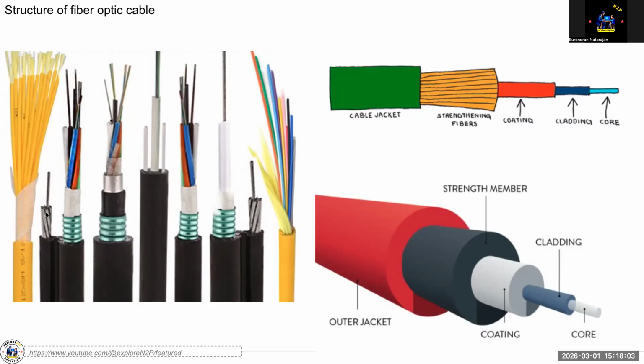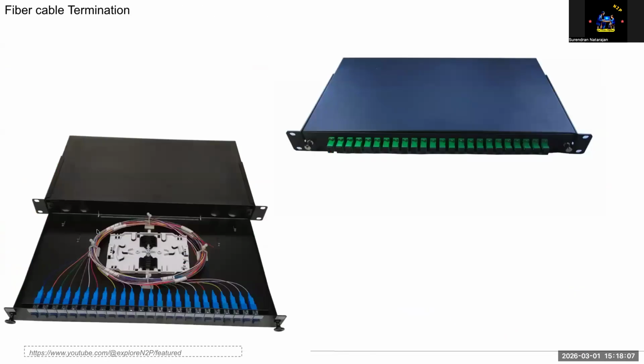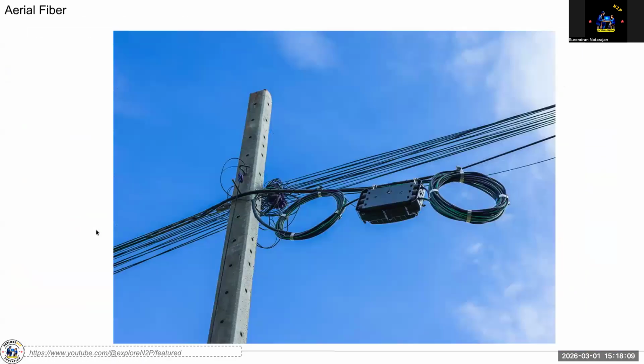These are all specially for protection. I will show where it is used now. It is used in this kind of setup. See, here you are hanging the fiber. If that is not used, then the fiber inside the fiber cable will break. So this is what I was talking about, macro bending, the coiling. If you make small circles, then it is gone.